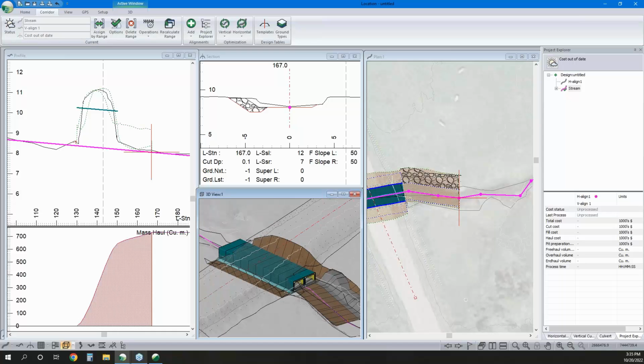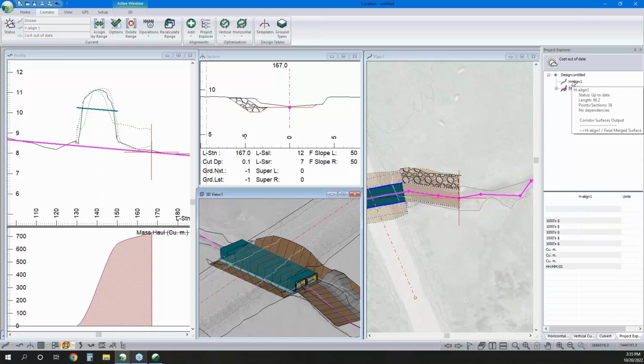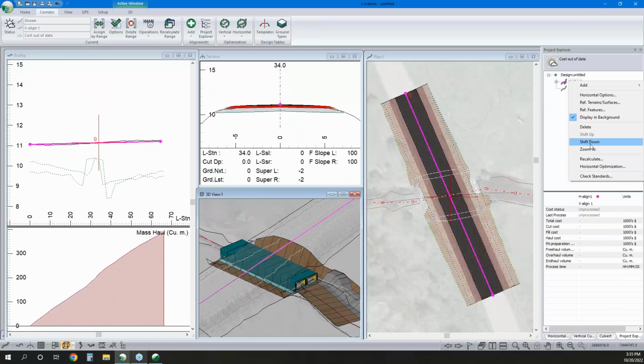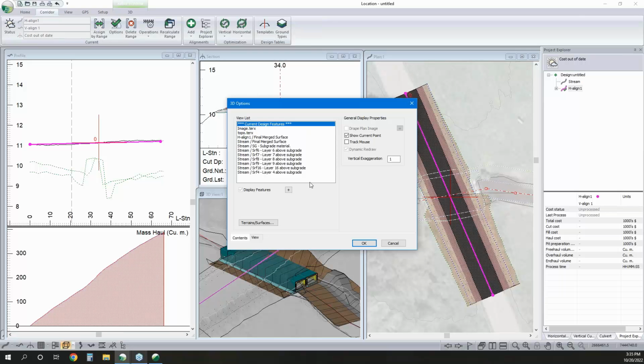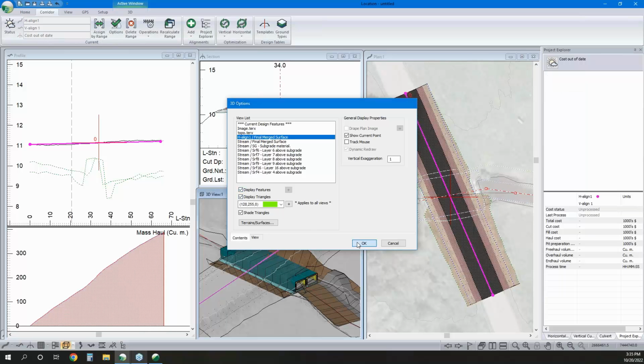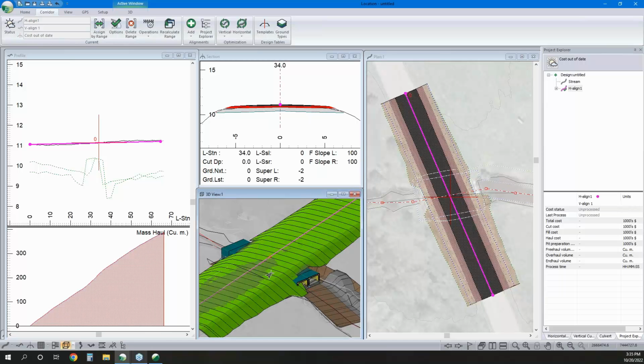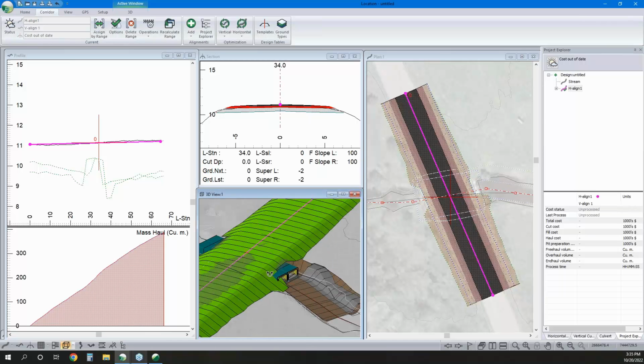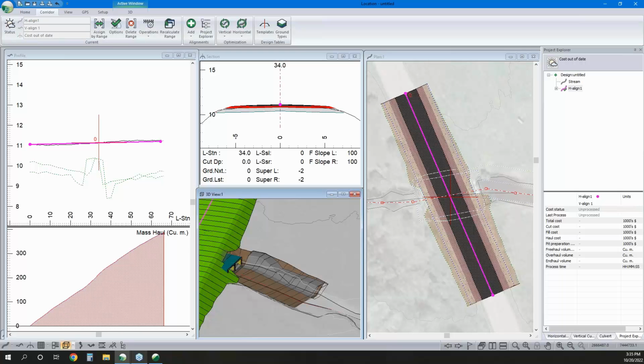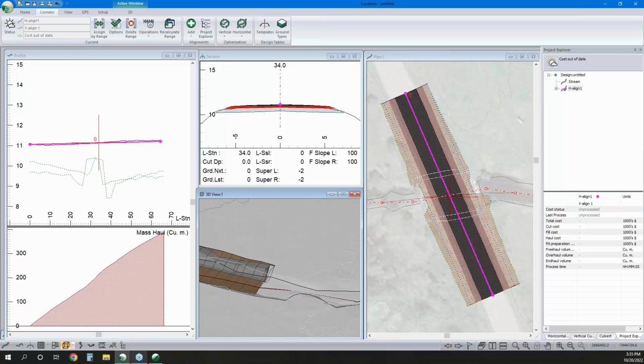Now let's go back into our roadway. I'm going to shift this down. And of course, we could show our different pavement structures here. I'm going to cheat though, rather than clicking that in. We'll just show the final merge surface. And we can see where we're popping out. Maybe I could use a little extra length on that downstream end.